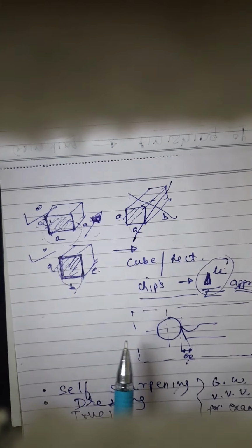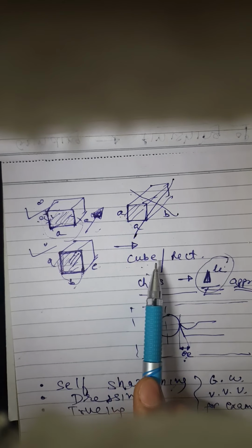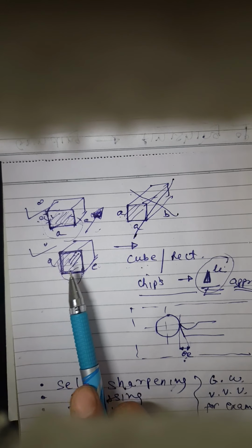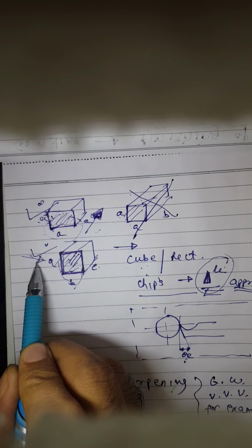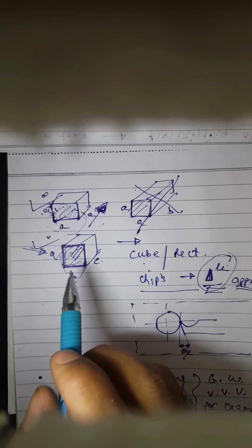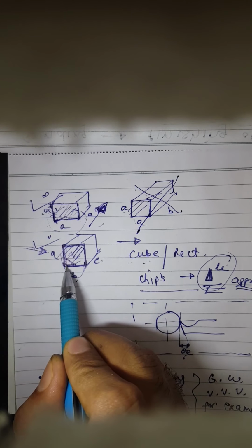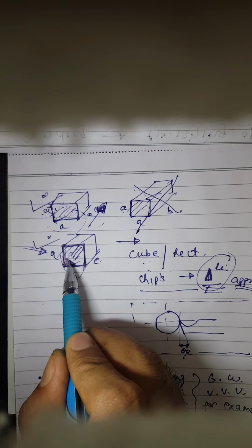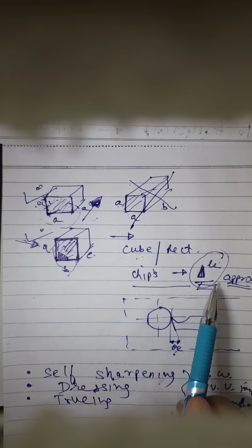All right, so assuming that the approximate shapes of these abrasive particles are cubic or rectangular, based on this assumption, if you could recall your concepts of EG, then a view from this, if you view this particular particle from here, and if you could consider a small part of this particular particle which is performing the machining operation, this much portion, then the shape of the chip that you may get would be approximately triangular.